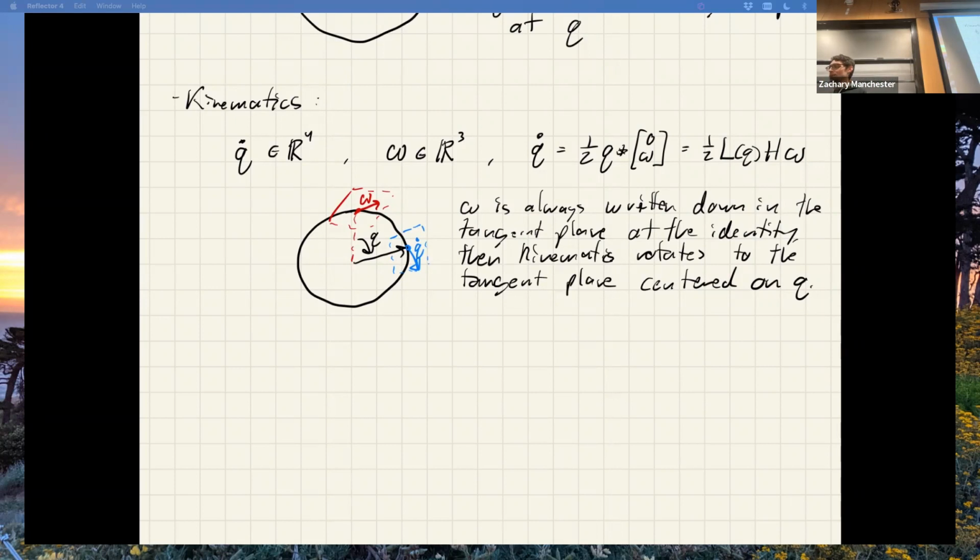If you look up the kinematics that map omega into Q dot, there's a similar kinematic relationship between omega and Euler angle dot, like roll, pitch, yaw. It turns out those kinematics are god awful, full of singularities, super nonlinear and really bad. This is the gimbal lock stuff, all this badness. These quaternion kinematics are globally well-defined and bilinear and about as nice as you can get.